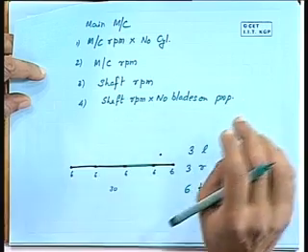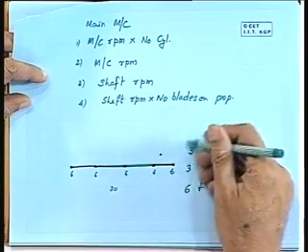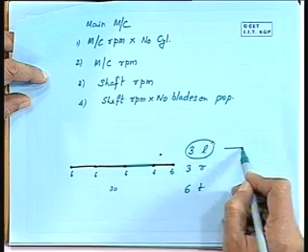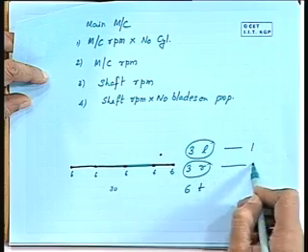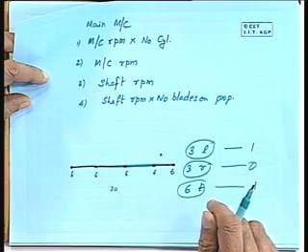So, then we try to say how we reduce the degrees of freedom. Out of this 6, when we talk about a ship's vertical vibration, then we are not considering the horizontal vibration or the longitudinal vibration. So, the 2 displacements we eliminate. We do not consider the torsional vibration in any of these axis system. So, from these 3 lateral we choose only 1, and from these 3 rotation we choose nil, and then the total degrees of freedom reduces to 1 at one point.